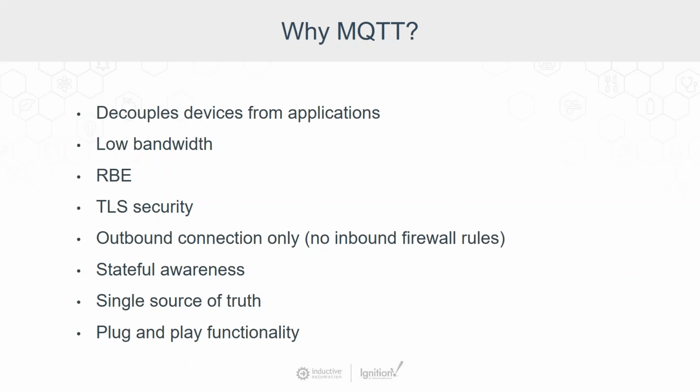The other big part of it is that it can provide a single source of truth, because if we get a new sensor that comes in that's brand new, we buy it, it supports MQTT natively, then there's absolutely no mapping whatsoever in that case. The device has the data that we need, and it's going to publish it up, and then applications can automatically discover that data. And that's a big part of MQTT, is auto discovery of tags and the data from the application side of things.